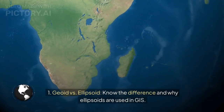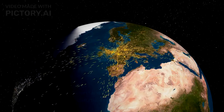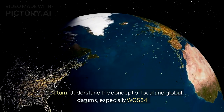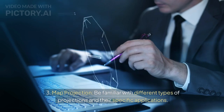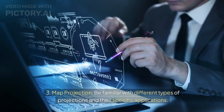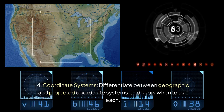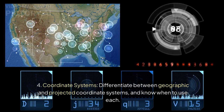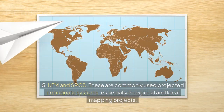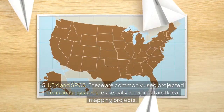1. Geoid versus ellipsoid. Know the difference and why ellipsoids are used in GIS. 2. Datum. Understand the concept of local and global datums, especially WGS84. 3. Map projection. Be familiar with different types of projections and their specific applications. 4. Coordinate systems. Differentiate between geographic and projected coordinate systems, and know when to use each. 5. UTM and SPCS. These are commonly used projected coordinate systems, especially in regional and local mapping projects.